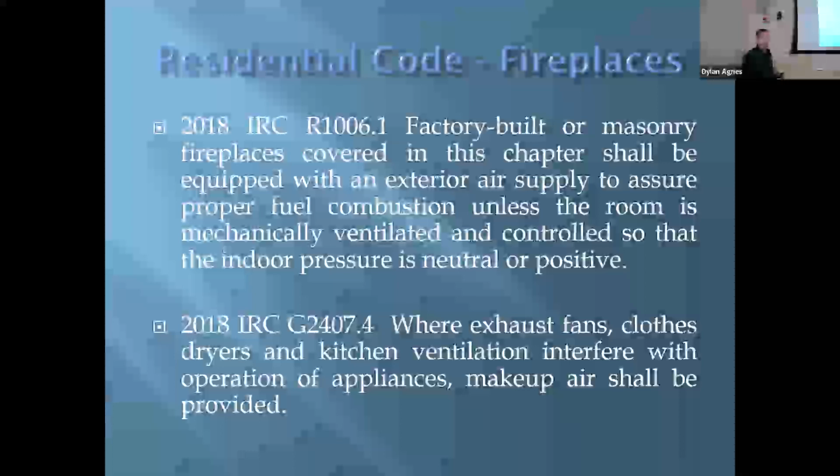One of the problems is that in new houses, the dryers are never installed. So you either have to use an inline fan just sitting on the floor to simulate it, or you run the test without it. So there are 2 tests: what I call the natural state of the home and the worst case scenario. I don't usually run all those in the middle. So if you have all these things running, appliance, ventilation, then you would have a very negative house.